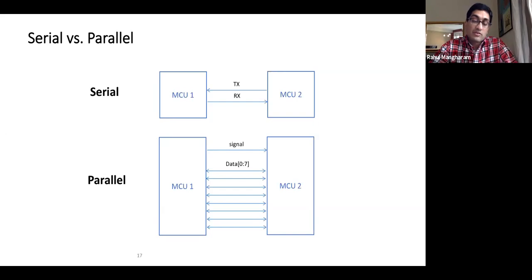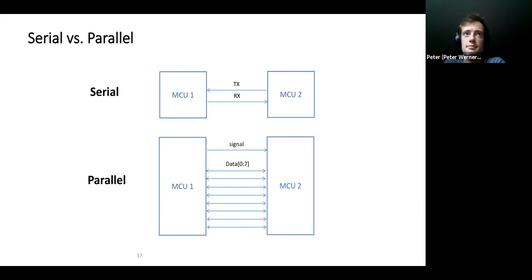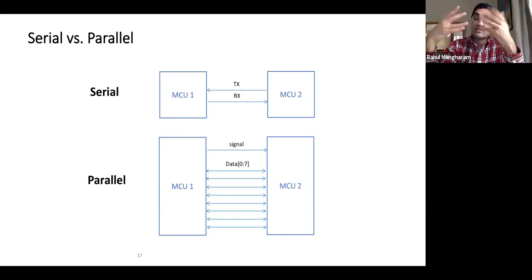That could be, but if you have fewer pins and you're sending the signal in a serial line, then I could be sending the bits too fast, and they could have inter-signal interference. That means between one bit and the other bit, they overlap each other, because there is some impedance in the channel itself. The channel is not at the same density, and the receiver is also receiving, like in a wireless channel,